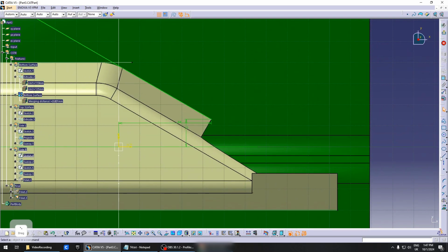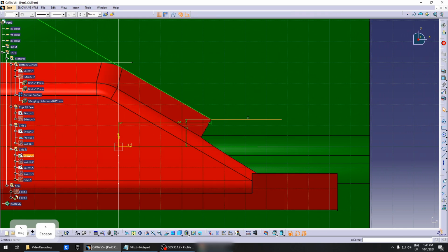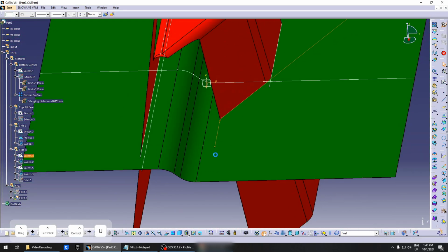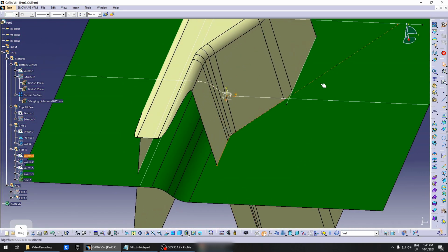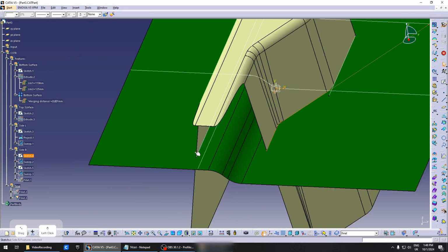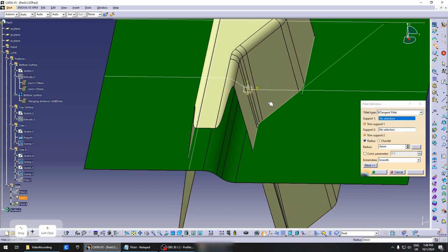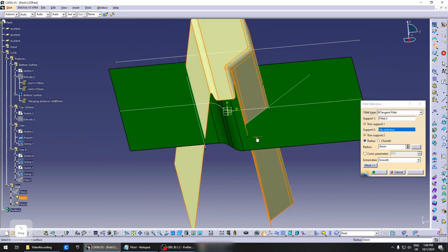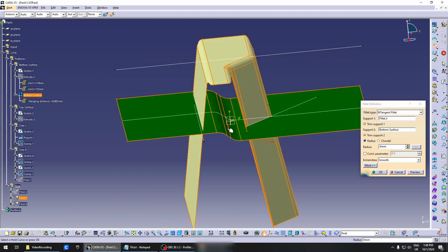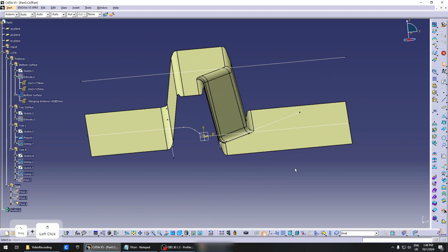And we also can do this, change this to something like that, and we need a small radius here. So this way, when it tries to create a fillet here, it's not pointing towards the other fillet around here. So it does have its quirks, CATIA, and you probably need to learn all these essentially debugging methods. There you go.